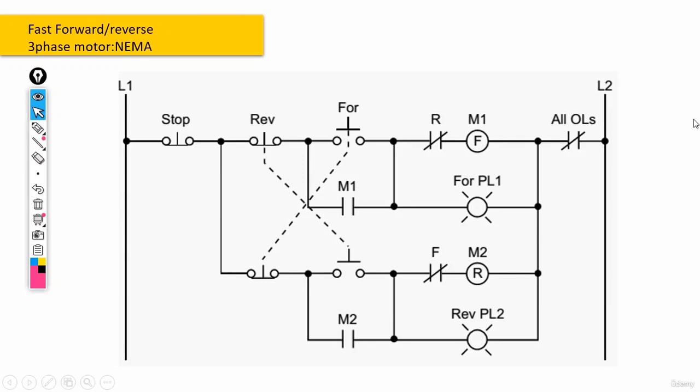Now, first off, let's go through the panel itself. Let's see what we have here. First and foremost, guys, this circuit that we can see here, this diagram, is for a control circuit. Let me write it down. Now, this control circuit is set in between two phases, L1 and L2, which are actually feeding this control circuit. We have this stop push button, and on this side, we have a normal closed contact of an overload relay, or a bimetal. And as you probably already know, the contacts are 95 and 96.